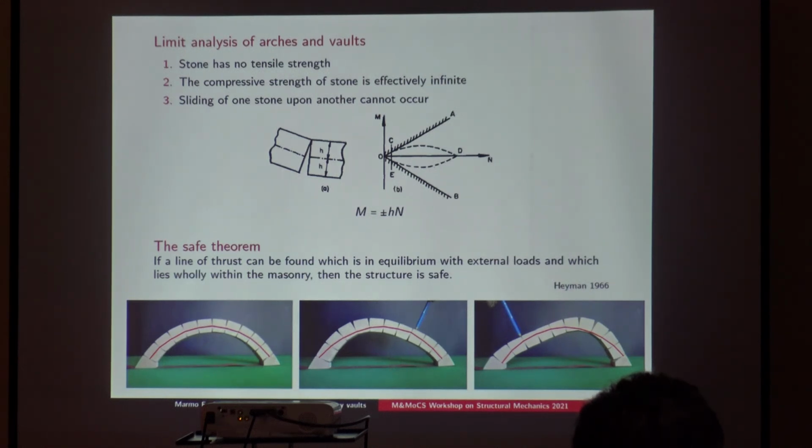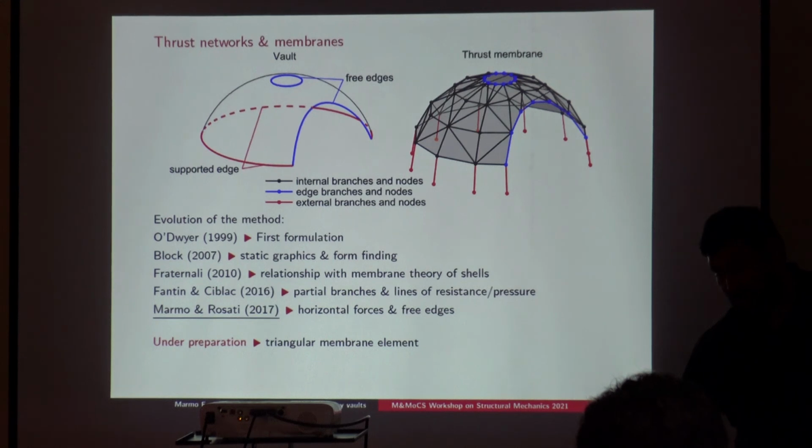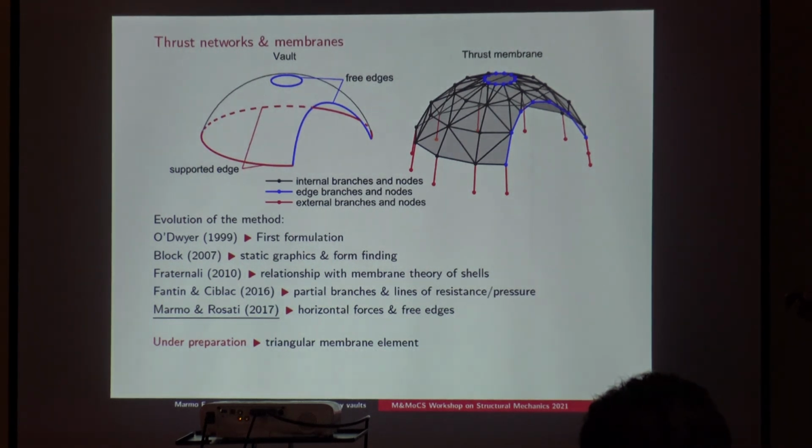The strongest sensitivity is on the topology. So if you choose a certain orientation of branches, these influence the solution. For the concrete dome, the topology is the topology of the fracture. The topology is represented in the model by the connection between the nodes.